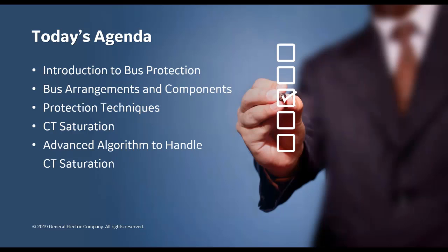So today's agenda: we'll go through a brief introduction of bus protection. The time is really not enough to go into a lot of the details in setting and calculating bus differential settings. So most of the discussion will focus more on the protection techniques, bus arrangement and components within a bus, some CT saturation and how those affect bus protection, and some advanced algorithms for handling CT saturation.